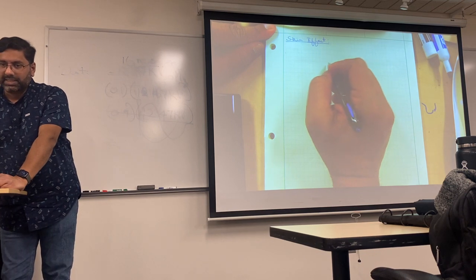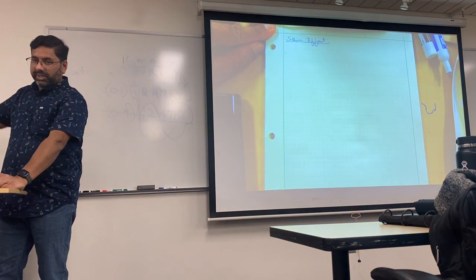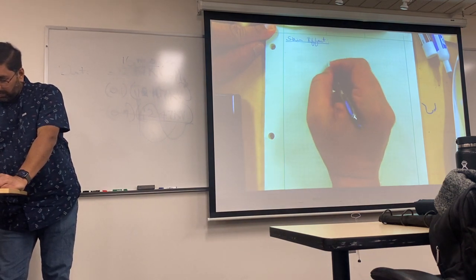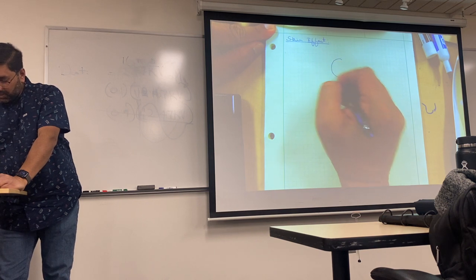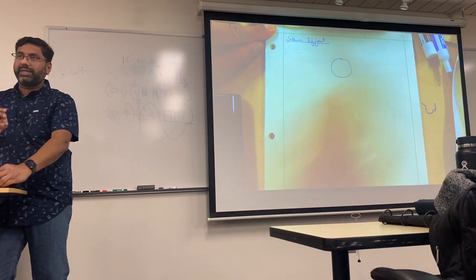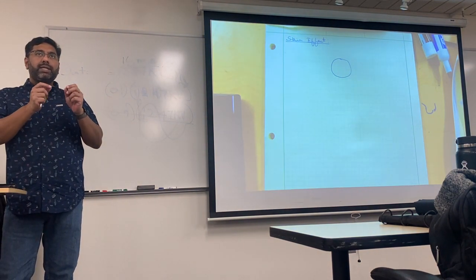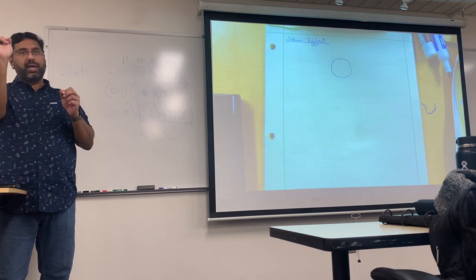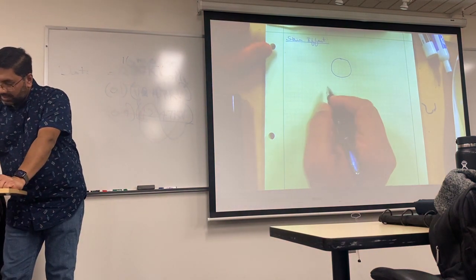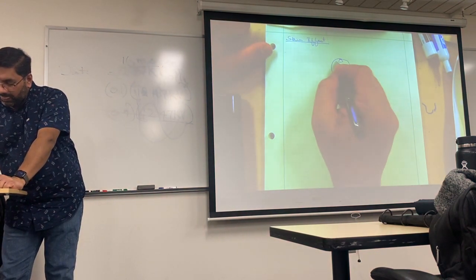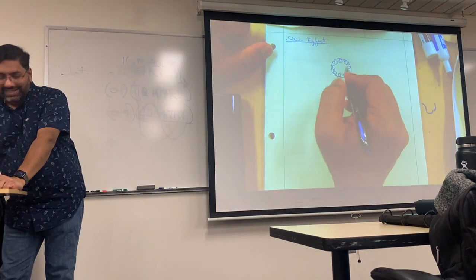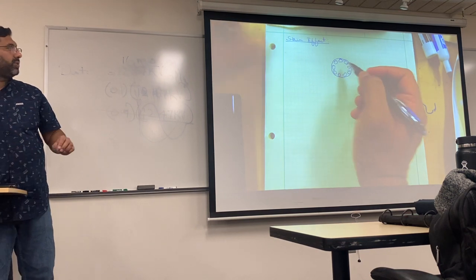So, any conductor that you see on the roads or next to your house that's owned by one of your power utilities, PG&E or Pacific, you would see some sort of a big conductor, and it would be twisted. If you zoom in properly, you could see that it's not just one strand of cable or wire, it's several strands that are twisted together. The skin effect is a property where AC current actually likes to flow through the surface of